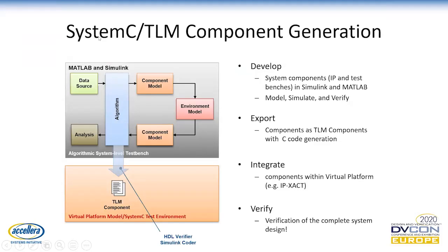It's a similar approach, a mirror approach to the DPI-C part, where you can generate SystemVerilog for different parts of your model. You can also generate SystemC TLM components in order to verify your environment in the software environment together with your software component. So again, it allows you to do verification of your system, software and hardware together, in early stages of your design, and of course growing with it. But already in early stages, you can test the integration of the different components that you have already. How do they work together?